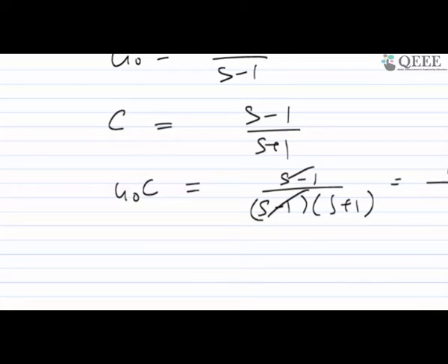This will cancel out and it would be 1 upon S plus 1. And if I use this under the Nyquist stability theorem, now there are no poles in the right half plane, so the result would be wrong. So I need to consider these poles and zeros as they are while plotting the Nyquist plot and analyzing the stability under that theorem.